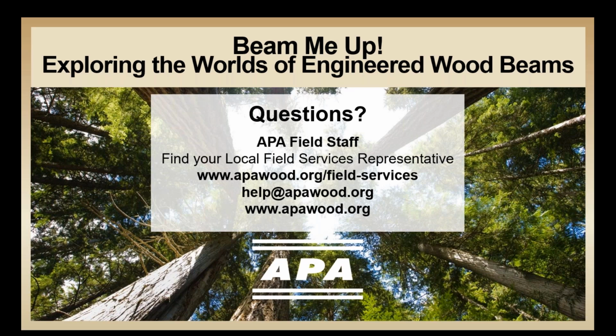Well, the answer to your first question, it's a little challenging, and they both have positive attributes. A built-up beam is often easier to assemble. It can be built up in place, allowing the framer to more easily handle the product as compared to a wider section. It's a lot easier working with lighter pieces. Whereas a solid beam, you may require additional equipment to handle it. You may need to bring a crane out or something like that with a solid beam.